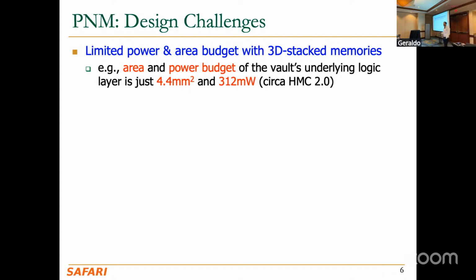The memory manufacturers are not including it for you to put whatever you want. Basically, it is there for interfaces like the PHY interface or some portions of the memory controller. They are going to be sitting over there so you can drive the 3D stacked memory above. So after the memory manufacturer puts the logic that they need over there, there is some free space available for you to include your logic.